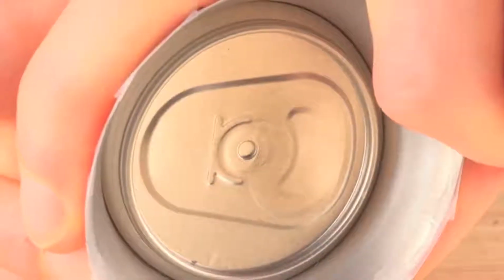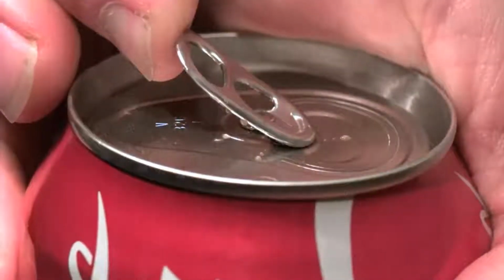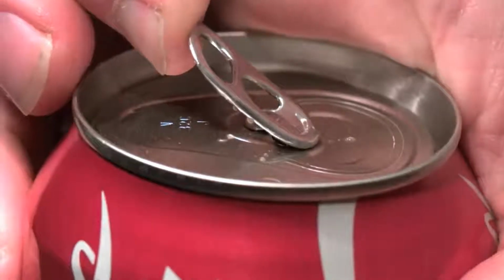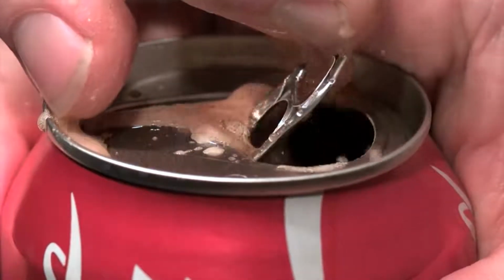Looking from the inside of the can, you can see how the tab first opens near the rivet. If you try to simply force the scored metal section into the can using the tab as a first-class lever with the rivet as the fulcrum throughout, you'd be fighting the pressure inside the can. The tab would be enormous and expensive.